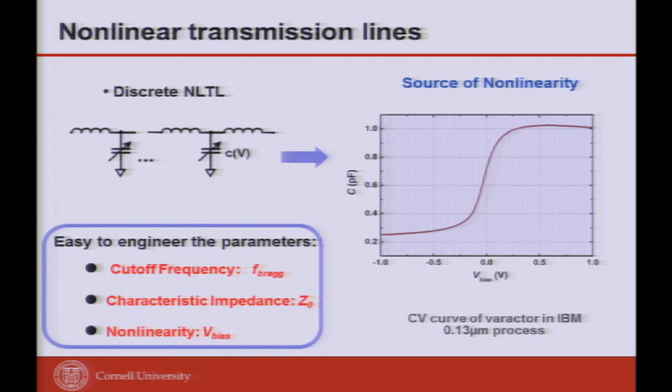But when one of the tape-outs is wrong, they flipped. So only the nonlinearity matters, but we measured a very gigantic harmonic conversion. So look at this nonlinear transmission line. There are a few things that are not in the original, just one L and C. The first thing you notice is that if I put it into a lattice, it gives you a Bragg frequency. Bragg frequency means over some frequency, there's only an evanescent mode. There's no active propagation above some frequency.